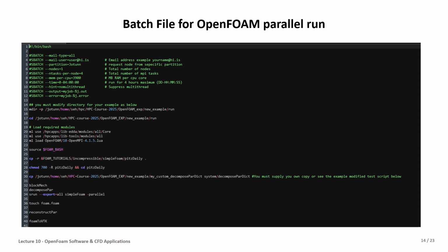Then we are doing the setup on the directories, and here we're only running the command for decomposition. You should pay attention when you are doing a copy of the example. You can go to the directories of the example and select your method for the decomposition. For example, you can run 3 times with different methods, and you can see the difference in computing time and also the difference in the result. Therefore, in the batch file, we are not doing anything regarding the decomposition method. It needs to be done from the directories.